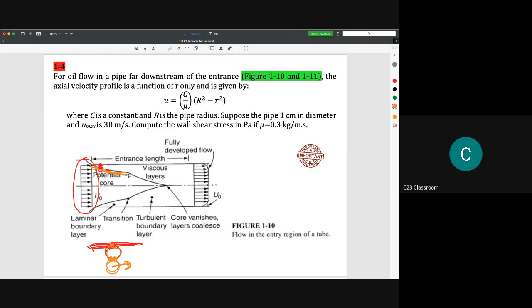This is why we have another second curve here, because it shows us the development of laminar and turbulent boundary layers. We learn about boundary layers later on in chapters 4, 5, and 6. But why do boundary layers occur? It is because the no slip condition gives us a different velocity distribution. And because the flow is in a pipe, the cross section area, the diameter, is fixed.